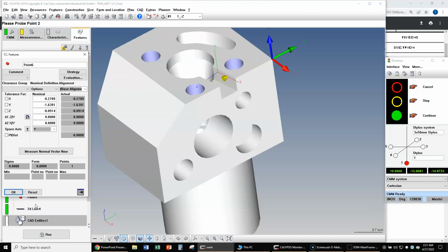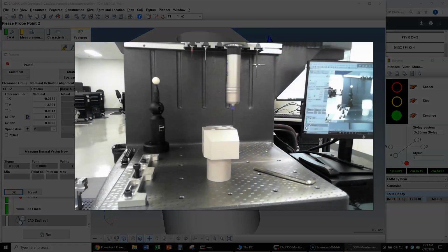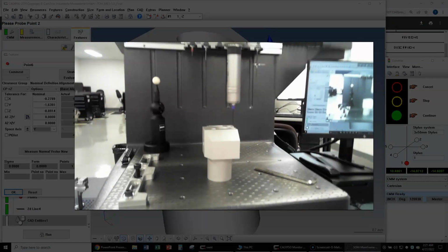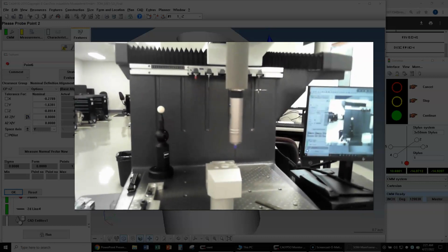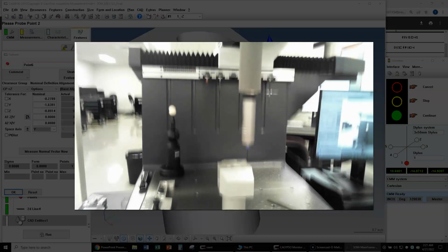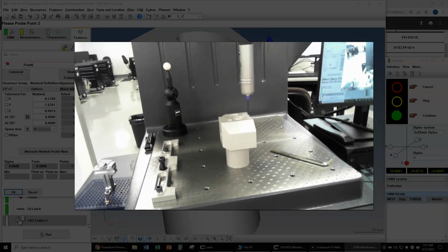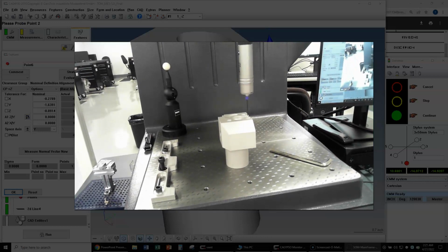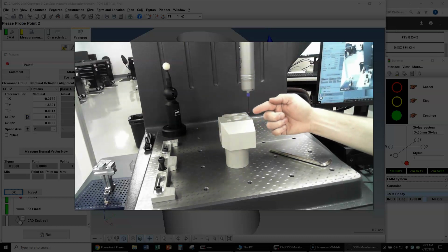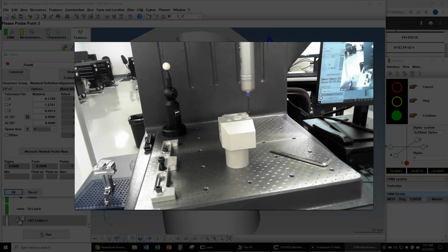But another thing I saw is that the retract value was set so that it was wider than the slot. In other words, the probe was coming down on top of the slot like this. Right? The default retract value in the software was a little higher than it needed to be. Sorry for giving you motion sickness here. I don't know if you can really see that. But basically, if the probe comes in too far over to one side, it's offsetting itself from the slot, and it's going to hit the model on its way down.